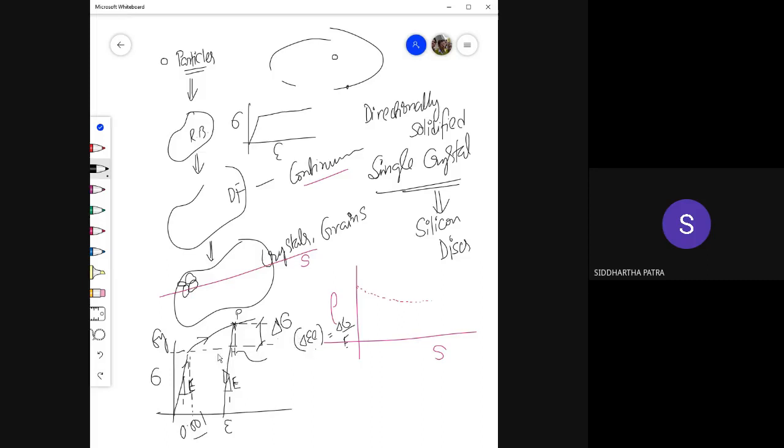Okay, and rest of what has happened, beyond this value, beyond elastic limit, a total of this much strain has happened. But out of that, this much is elastic. And when you unload, whatever has been elastic, that means you unload this portion that happened before having plastic deformation and this additional portion.